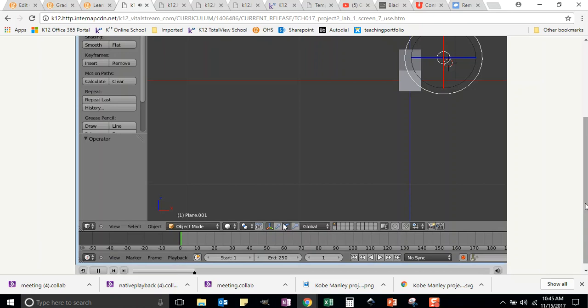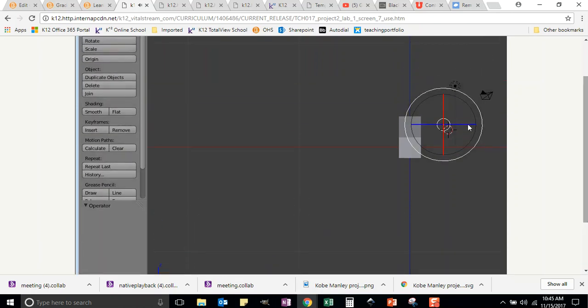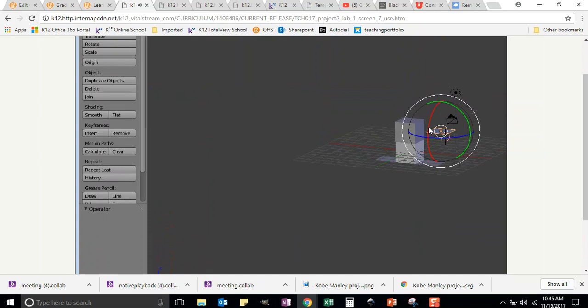If necessary, right-click the plane to select it. In the 3D Transform Manipulator, left-click the red circle to rotate the plane along the x-axis. You want to make the plane parallel to the house. Panning around the house so that you can see the plane from the side view may make this easier.